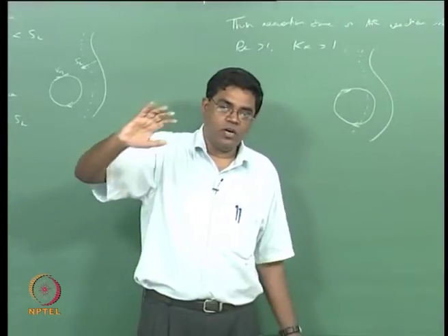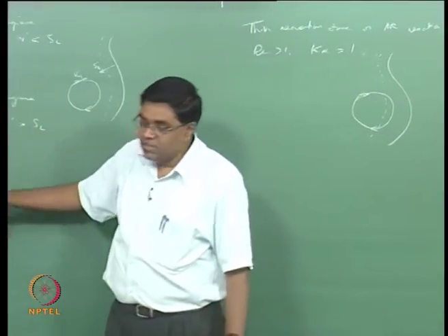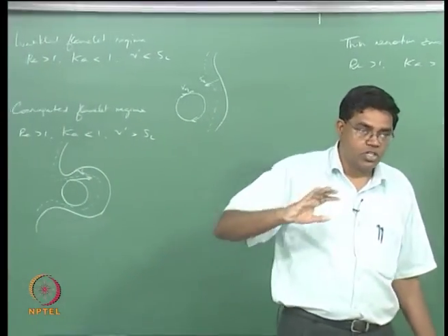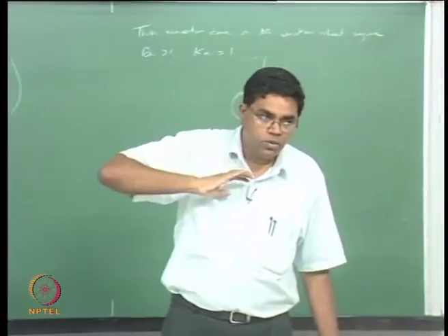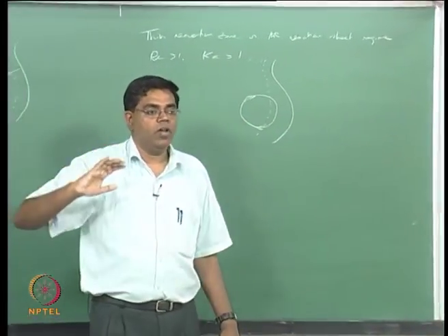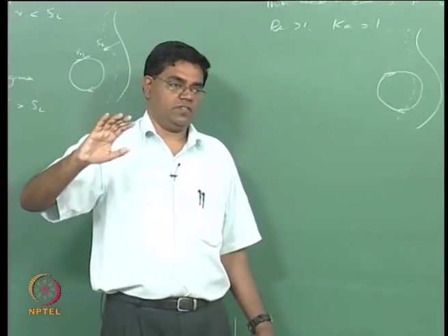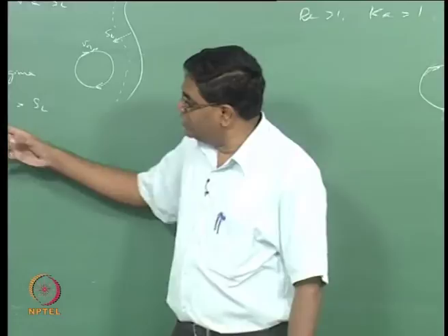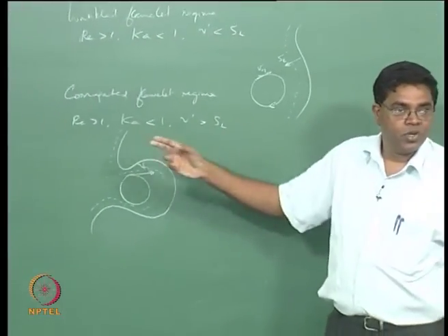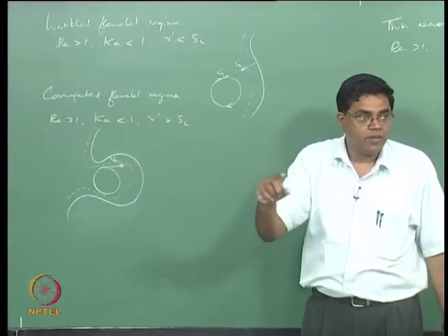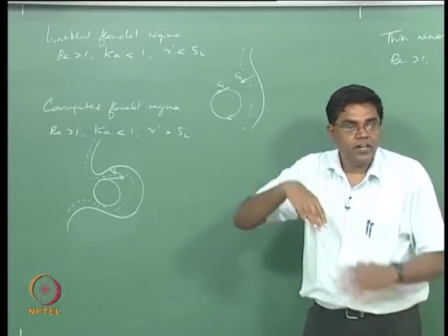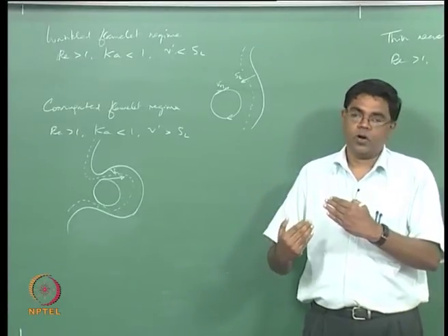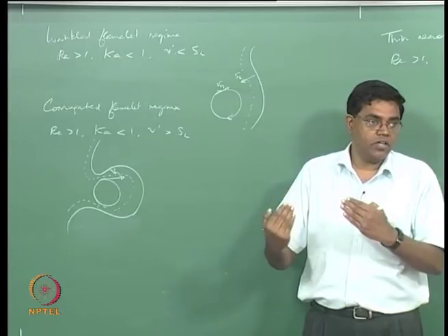That means in these regimes we can still continue to think about the turbulent flame or the turbulent combustion zone as being made of an ensemble of laminar flamelets, right. So locally where you have these things satisfied, you can say it's essentially a laminar flame, but it's now interacting with an eddy and therefore it's getting curved, wrinkled or corrugated, right.